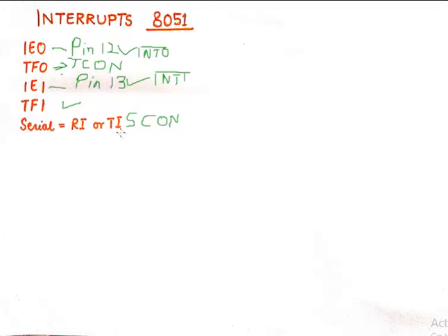So you'll get a signal of them becoming 1 or 0 in the SCON register. Now incidentally, all these interrupts are vectored interrupts, and that term is again very important, because if we study interrupts, we ought to know which interrupts are vectored and which are maskable. Vectored interrupt means whenever these interrupts occur, they take the microcontroller to a certain location where a subroutine or something of that sort must be written. So the microcontroller will go to that place to execute something.